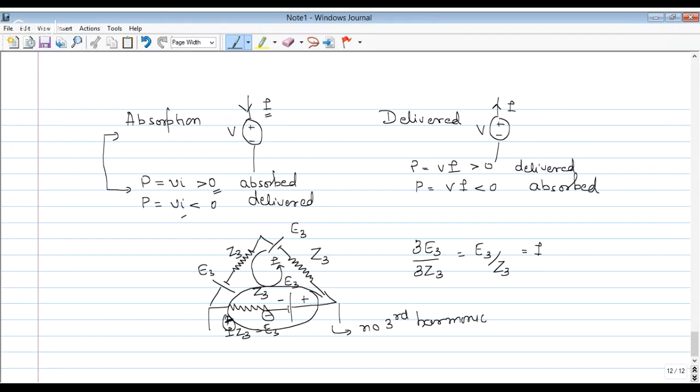So I have answered, Naveen, your other doubts. I have to see this 3-point starter problem. Starter for a DC shunt motor is not used where wide range of speed control above rated speed is required. So see, for wide range of speed control above rated speed, we need to use flux weakening. That is, we need to reduce the flux in order to obtain wide range of speed control.